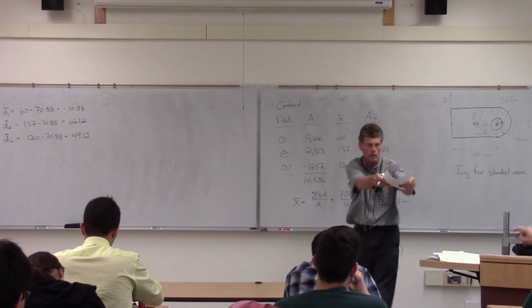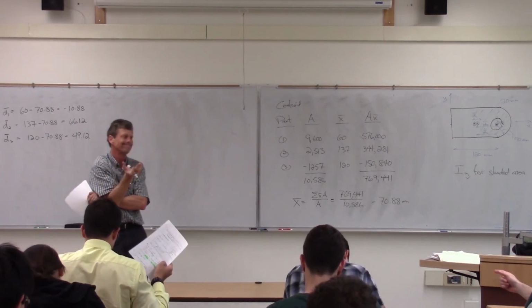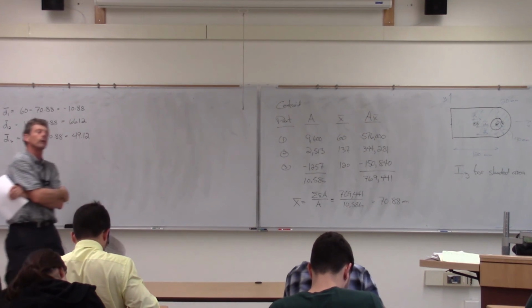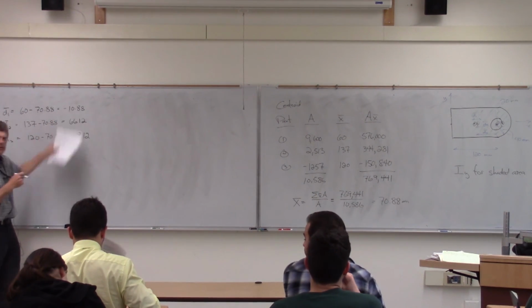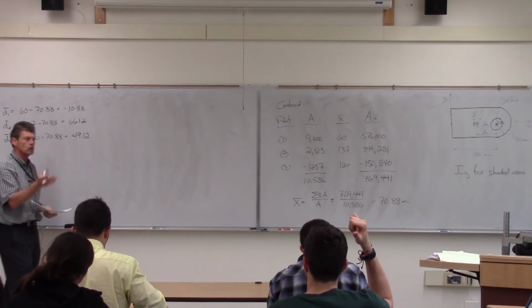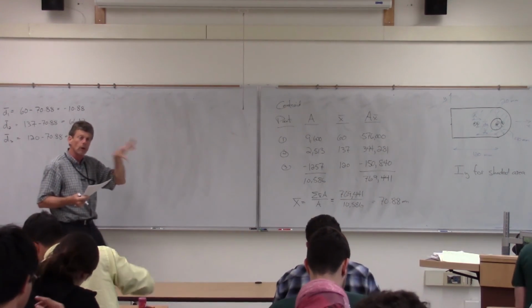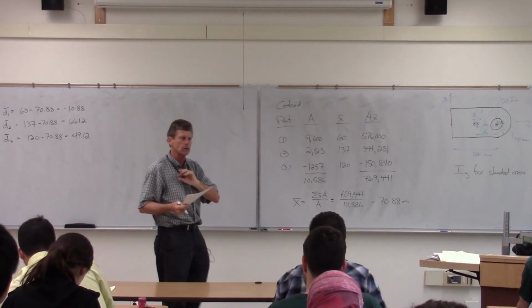Quick question. Sir, the 10 is negative, so when it's squared, it's going to become positive, so does that not really matter? Doesn't matter, yeah. Good point, yes. Remember, our d's are squared, so it doesn't matter whether it's positive or negative when we plug it into the equation. The one thing that does change is the area and the moment of inertia. We're going to put in a negative for holes in those particular cases.